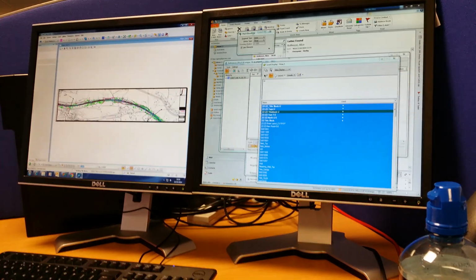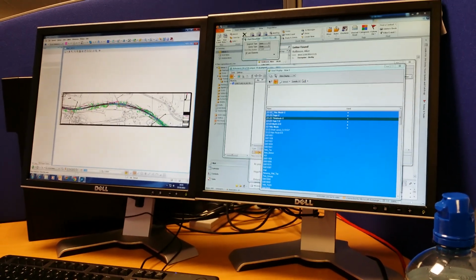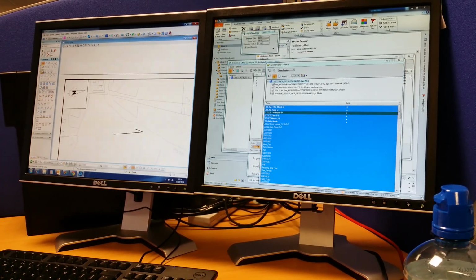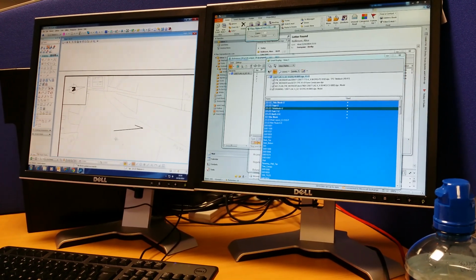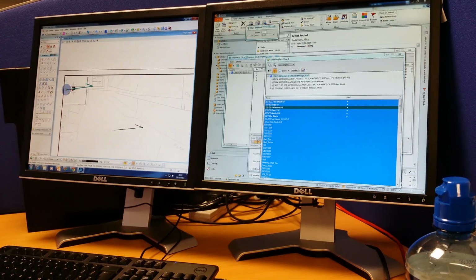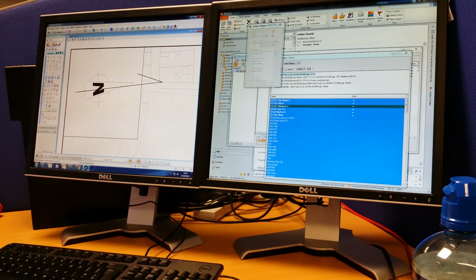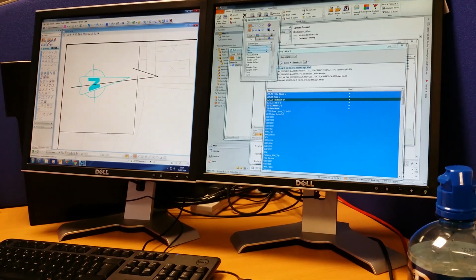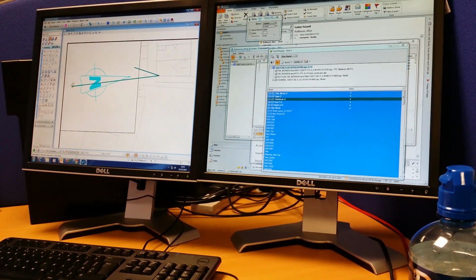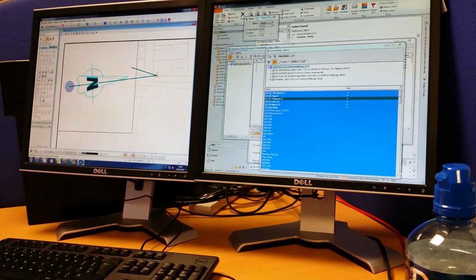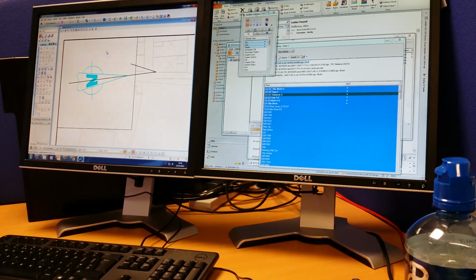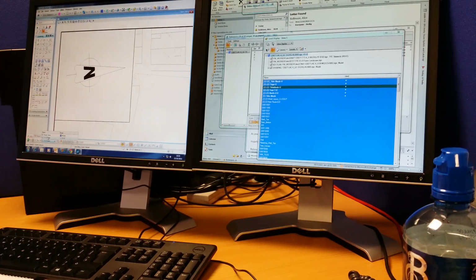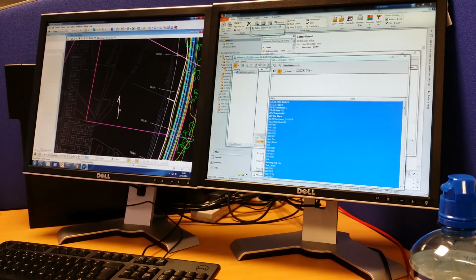As I say, only thing left now is to rotate the north point. So it's back into model view. Wait for it to catch up. And put a line in just to represent which way north goes. Back into sheet view. Quite a bit of chopping and changing between the display modes. So copy that line to the north point. Select your north. Rotate to suit that line, and then you now know that is the correct north. Delete that line. Go back into the model view. Delete.